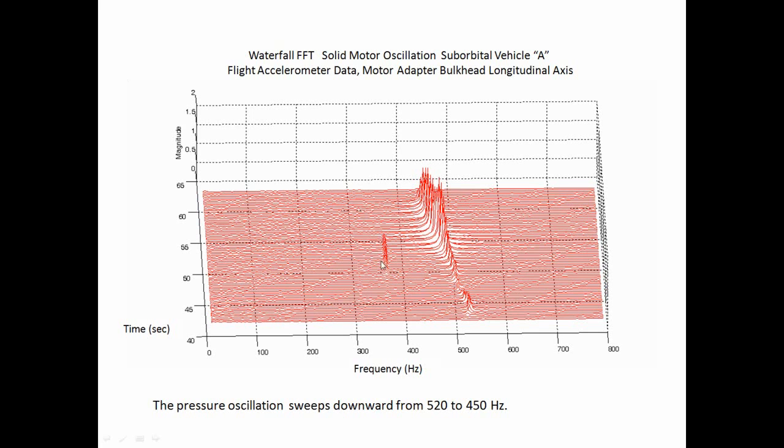There's another little sequence of peaks occurring at about 360 hertz, and I don't always know. Sometimes we just cannot identify what all the spectral peaks are due to. Was this due to some spurious noise or something else going on with the launch vehicle, or maybe the thrust vector control system? I wish I knew. Further investigation would be needed, but this was a long ago launch of this vehicle, so that opportunity has come and gone. So now we're going to look.